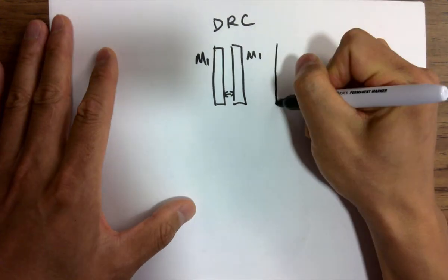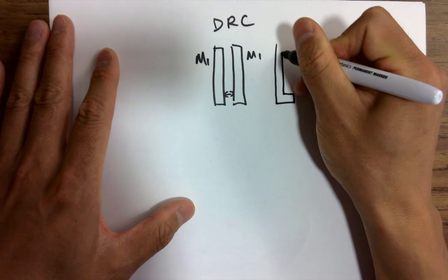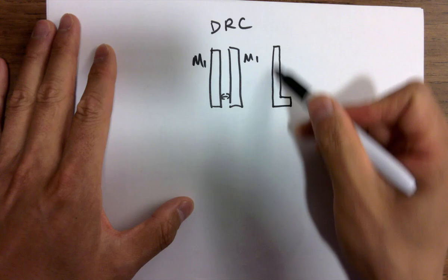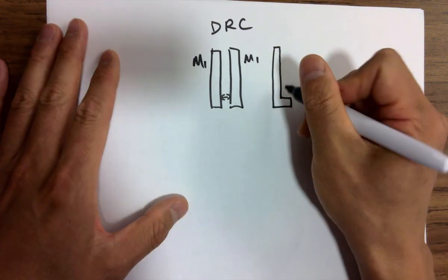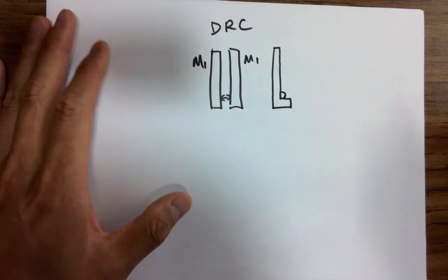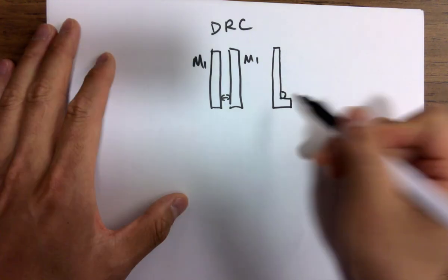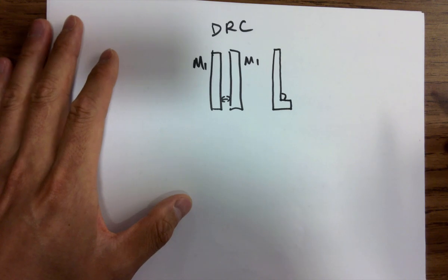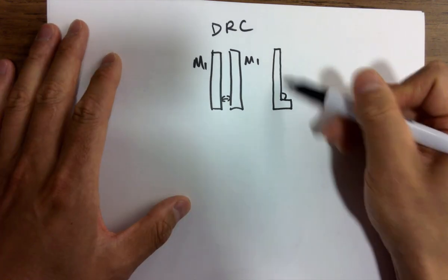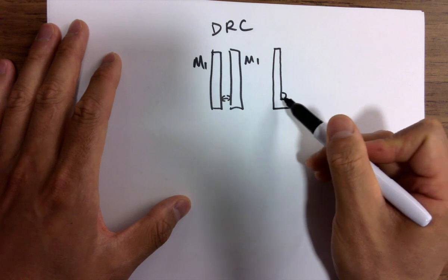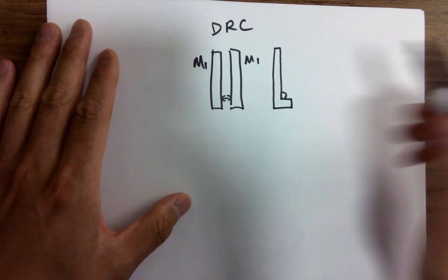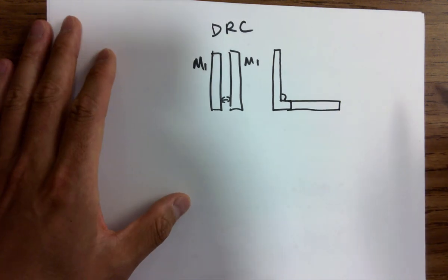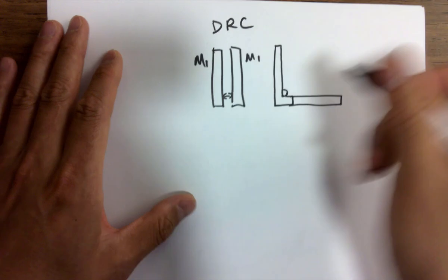However, you can make turns, because a lot of times you are making connections that require you to turn to the other side. So this little gap here, sometimes it's too small and it won't be able to resolve it. Be careful about that part. If it's marking a DRC violation here, you need to know that some of the very small turns cannot be resolved. So you have to make this longer probably, or things like this.